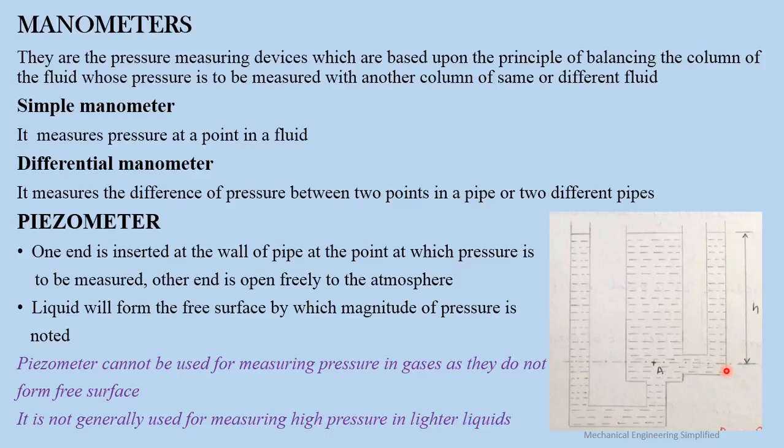water column. So you can just see, and if there is another liquid which is having a density much lesser than water, maybe some oil or something like this, which is having a density still lesser than that of water, then you can see that the height of that liquid column will increase further, more than 10.3 meter, and 10.3 meter is in itself a very big height. So this makes the length of the device very infeasible to work with.